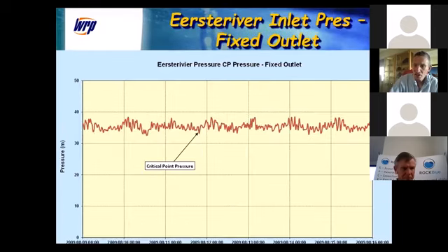The pressure at the critical point basically looked like this, which was about 38 meters. Now you could still take it down further. You could take it down probably to about 20 if you really wanted, without having a riot on your hands. But anything below the 38, we were worried about getting complaints. The client didn't want complaints. So a lot of the time you get a balance between complaints and high pressure. So we settled on 38 meters.